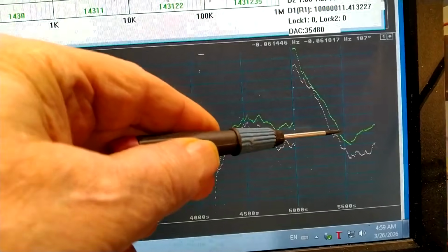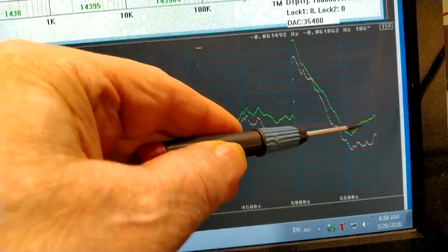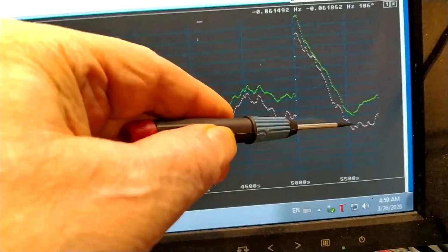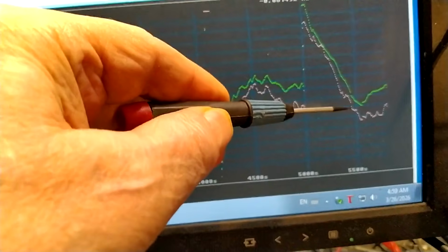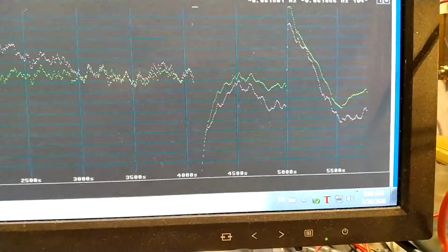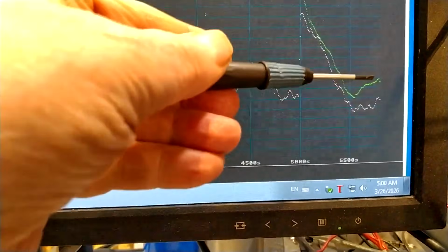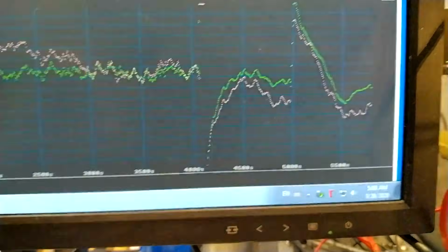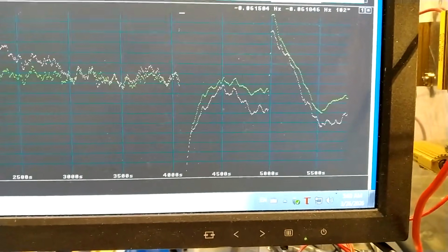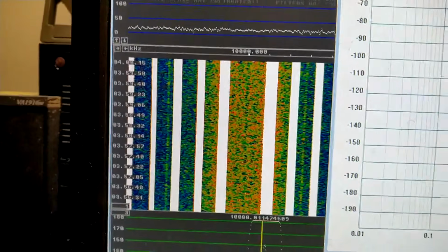And here there is a small frequency jump downwards and then upwards, and it is present in the red trace also, which means it comes from my 4-crystal oscillator. It made some jump, and also here, so I don't know the reason for that, and I don't see it here. This looks calm.